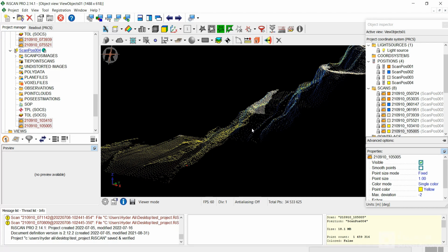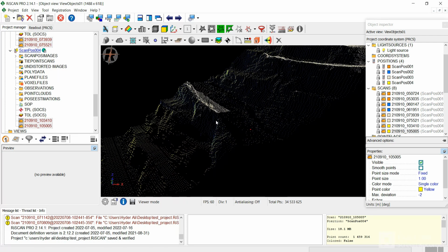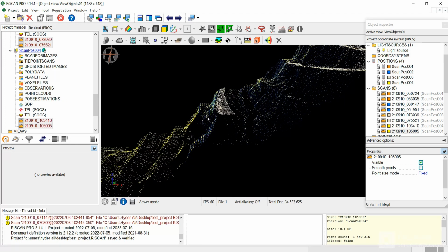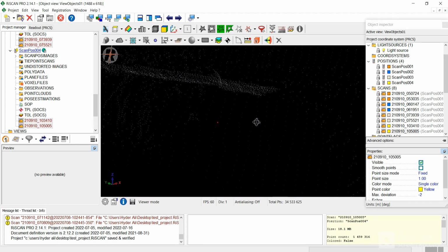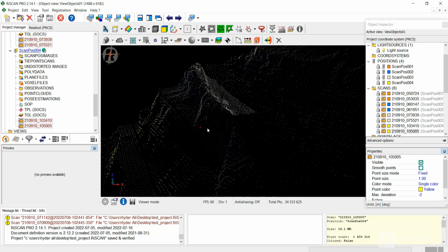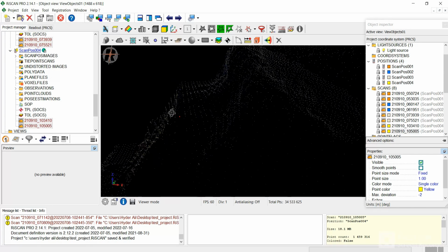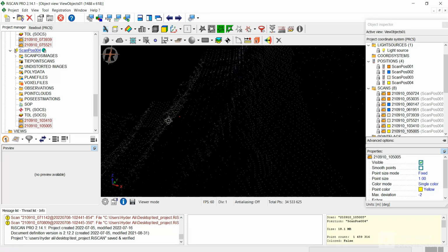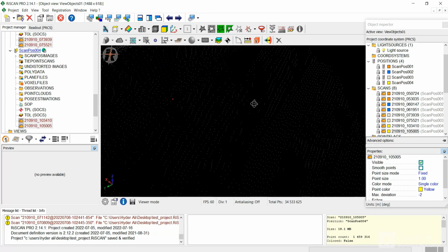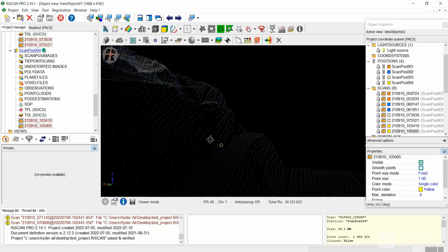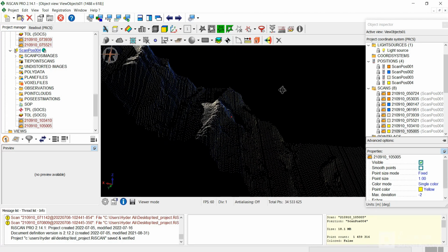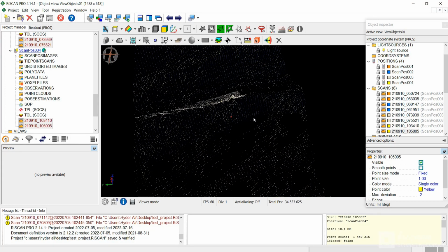We will see by checking the joints where two or more point clouds are merging, and if we see any inconsistency, like see there is white color and yellow color and blue color point cloud data, that means this particular area contains 3 point clouds and they have been merged very consistently. So we can clearly see the edges and the angles and everything. So it is quite consistent data here, and we hardly require any multi-station adjustment process here.